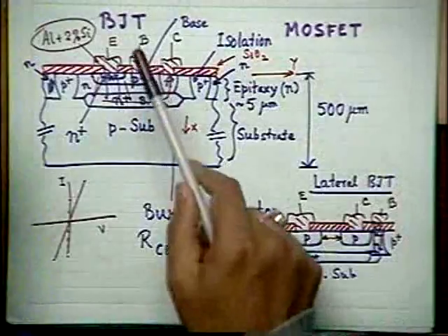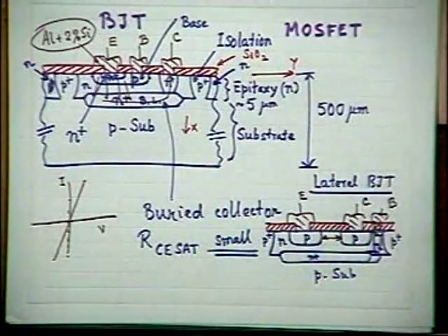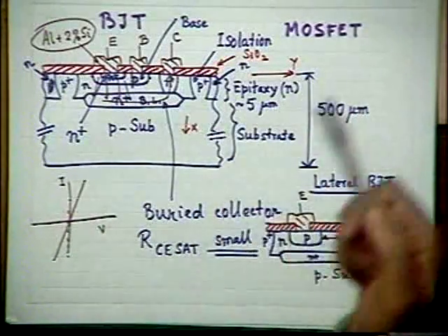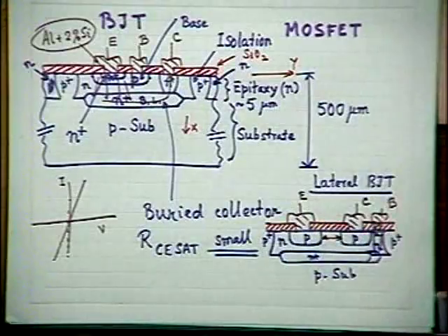Please remember this. Now, in order to optimize the performance of these transistors, which was perhaps discussed in the device class, we have to play with the following. What are the things we have to play with? One is geometry, the mask's geometry. Different dimensions, like what will be the emitter length, base length, width, etc. It is called the geometry of the masks. The first thing is the geometry of the mask. Second thing? Power delay, yes? Power delay comes afterward.